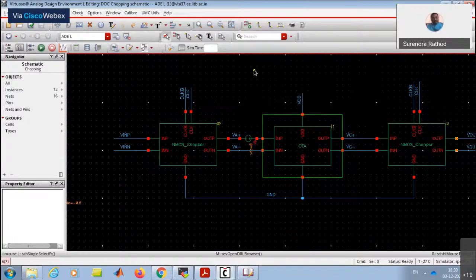Yeah, I think there are no more questions. The technology node affects the design. Yes, it will, because if you go to lower technology nodes, flicker noise is a bit improved. So noise performance-wise we will get some benefit, and the digital part, especially these clock sources, can be easily implemented. So you can go to much higher chopping rates, and that will give you a benefit in terms of speed for digital.